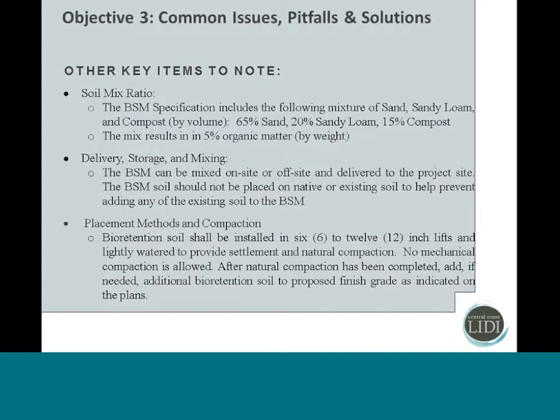So delivery, storage, and mixing. This can be done on-site or off-site. The key is to not have it mixed in with native soils. Placement methods, I touched on that, doing the lifts and natural compaction with light watering.